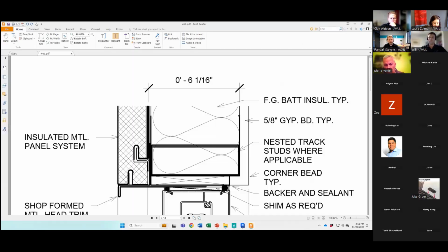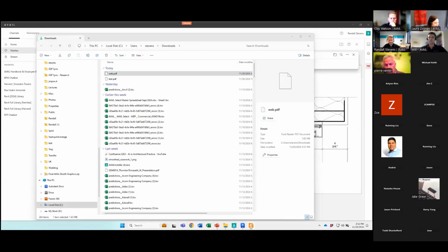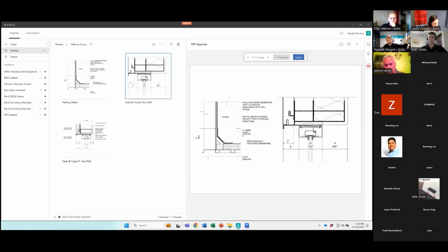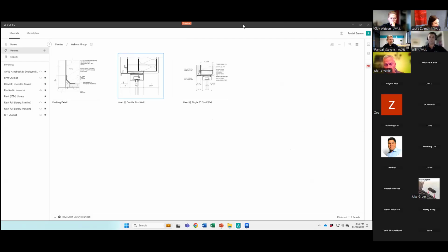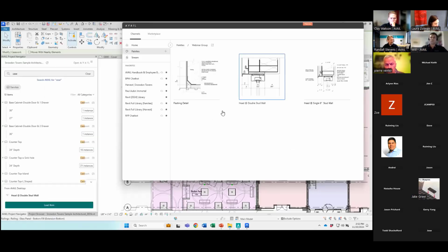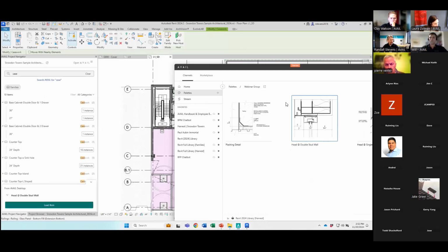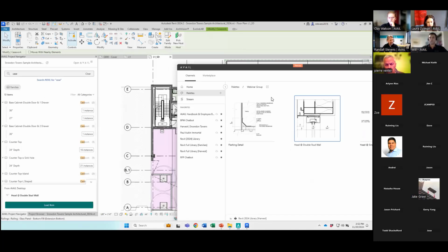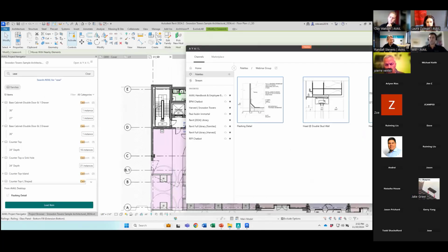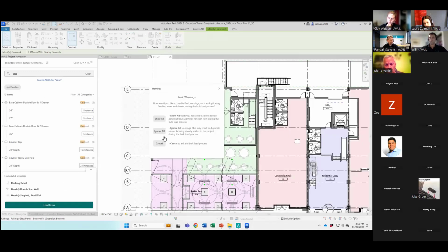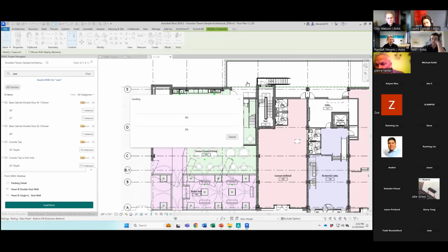And then, either through Teams or whatever communication, pass that on to Will and say, hey, you've got the palette. Here's the red lines for that. Go do your work. So then once you're in this palette, you'll notice that over here in Revit, your workflow, I could go multi-select those if I'm working in Revit off my palette and load all three of those at once into my project. We'll throw those normal Revit warnings up, but now I've brought those three details into my project where I can now go do work on those.